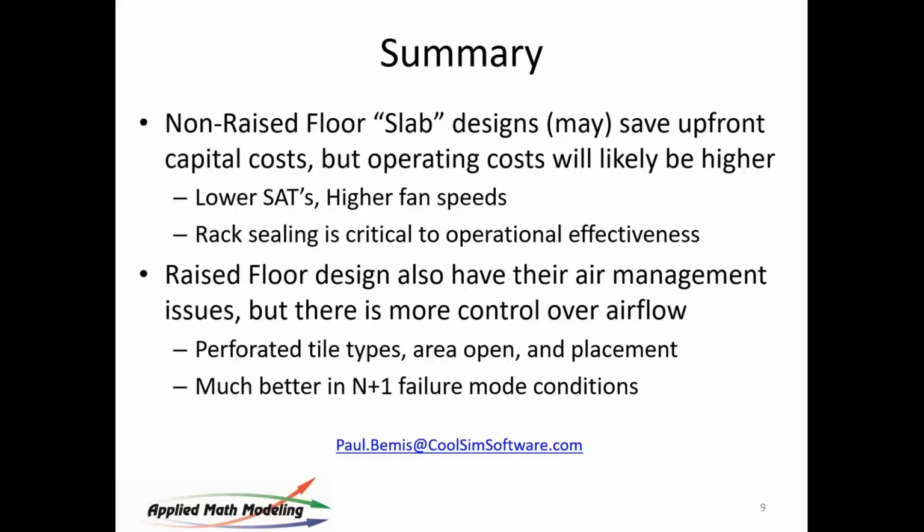If I have leakage and the room is not managed well from an airflow point of view, then I have to either run the temperature lower or the fans harder to make up for that. So where you can drive the amount of supply air more closely to that that's demanded by the rack in the raised floor design, you don't have that freedom in the non-raised floor design because you can't modulate the amount of air coming into the room. It's all been done by the big fan wall. So it becomes problematic.